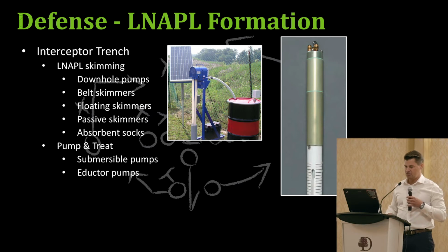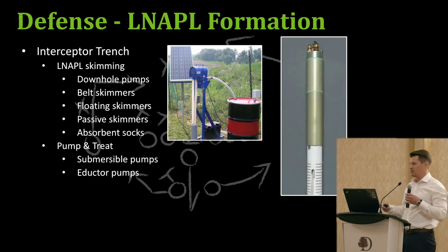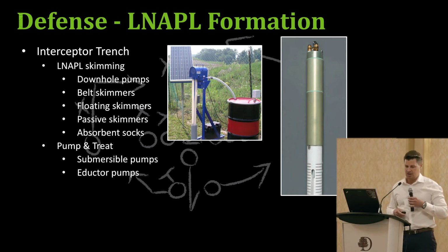You can also go with traditional means of pump and treat, where you're moving total fluids, but then you're having to separate the free phase, the free product LNAPL, from the water above ground, and treat the water and dispose of it. Or you can use suction pumps above ground, like eductor pumps.